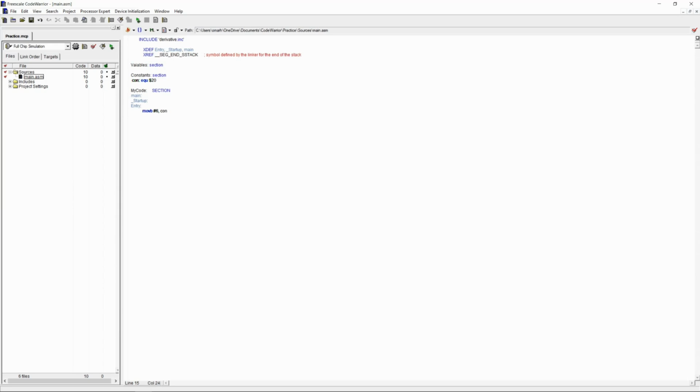So why would we need names for memory locations if we can just use the number? Well, because sometimes you want to make sense of memory locations. For example, if you have an output port that is an LED or a switch, and every time you're accessing it you write FF3 or something, instead of saying FF3, you want to say LED, and so the program now will make more sense. Same thing as with variables.